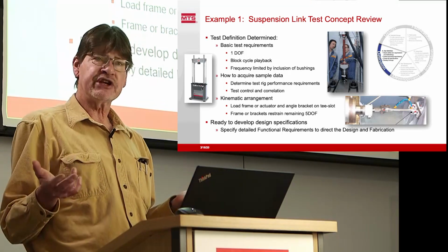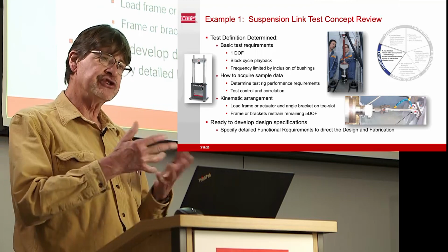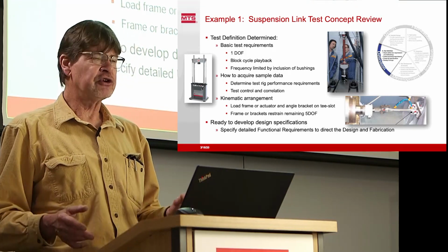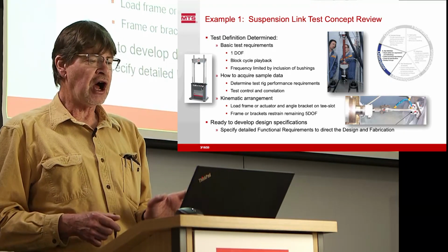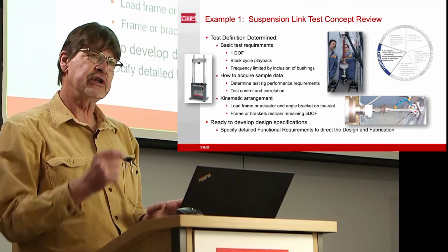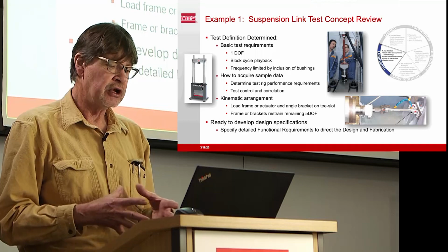How are we going to acquire sample data? We talked about instrumenting the part or inserting transducers into it. We need transducers both for control and for correlation. Control tells us how we're going to push on the part. Correlation says, is it responding realistically? Those are two different requirements and may need different transducers.